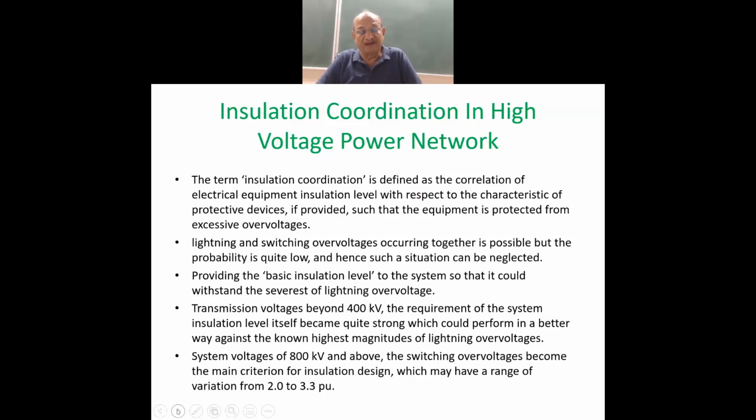The air gap electrodes used to get corroded, and there used to be expulsion type lightning arresters which would produce a flashover between the air gap and let the peak of the traveling wave be grounded.